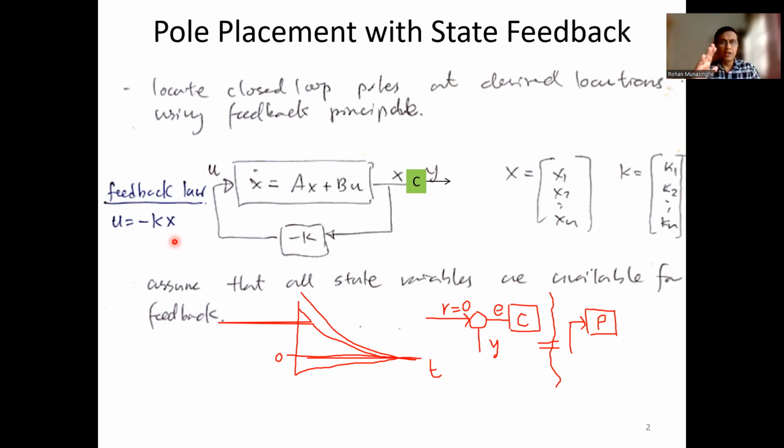If you want to move, let's say, an arm of a robot by 30 degrees, you send 30, but you keep the 30 intact for at least some amount of time, giving that time for the controller to move it by 30 degrees. And after that, only you put another command. Now go to 45, whatever. So during that time, your reference doesn't change. Maybe it's a small amount of time, but for the control system, it's long enough to drive the variable to that reference level. So if you look at that level, it is a regulator problem. But if you come out and see the whole process, it's not a regulator problem, it is a tracking problem.